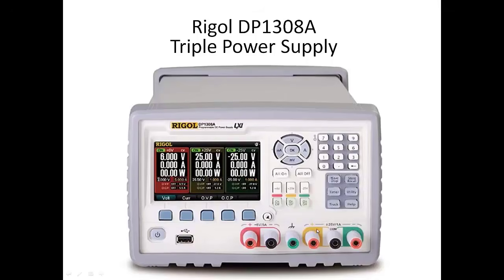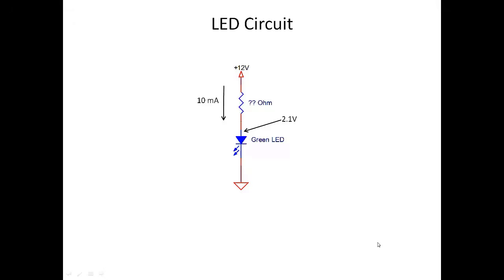Just to refresh your memory, the dual section are these three connectors on the right-hand side. Be sure to use the common in the middle, the black connector, for ground. And remember once again that the negative supply is on the right. The positive supply is to the left of the common. So don't end up using the minus 12 volts by mistake.